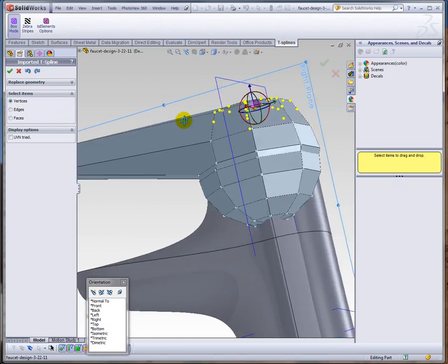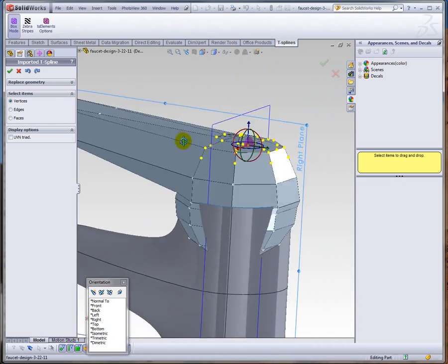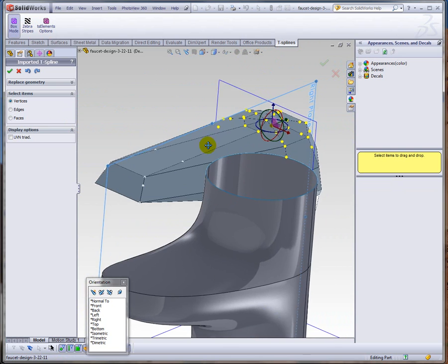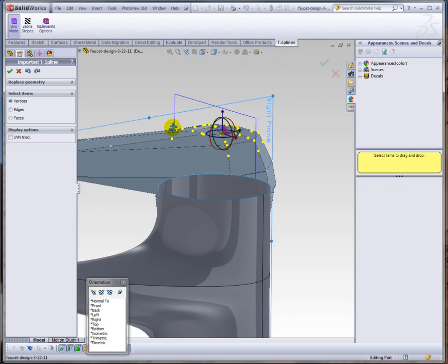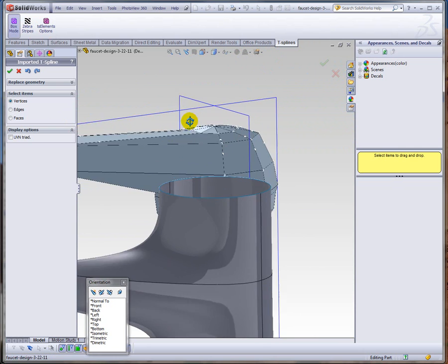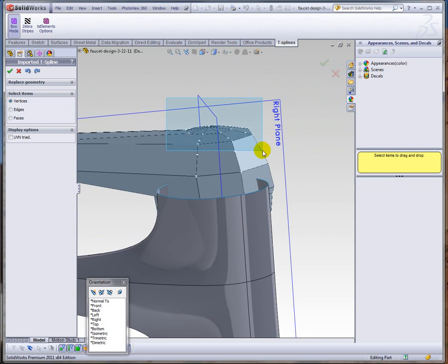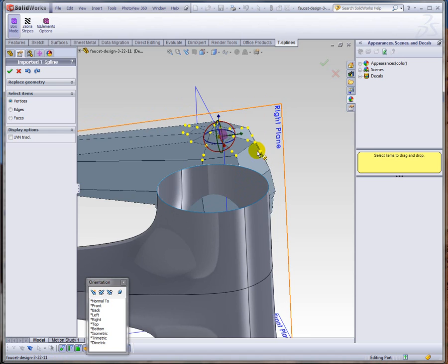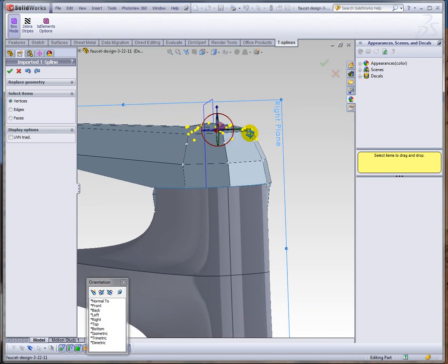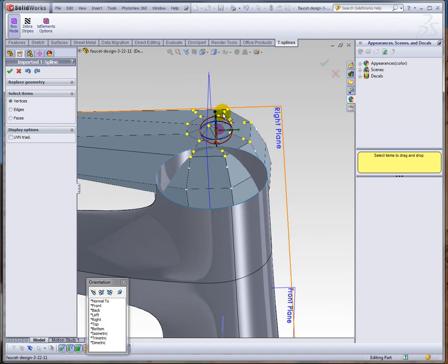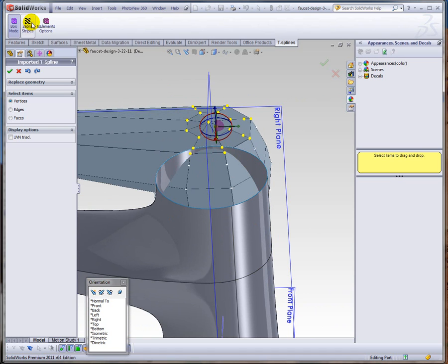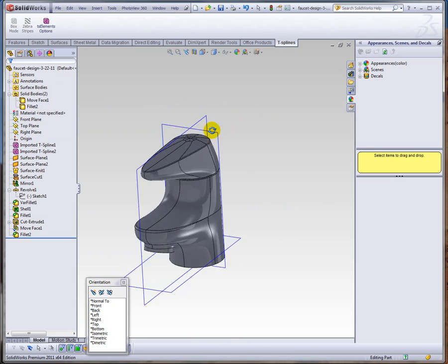So this is where the original T-Spline started, from a polygonal mesh, and so if it's easier for you to visualize, you can actually put it into this mode and pull on things using that. So if that suits your fancy, you can do that also. And then you can just turn off box mode, rebuild, and you get everything. So that's pretty much it for the time I have here, and show you how that workflow can work.